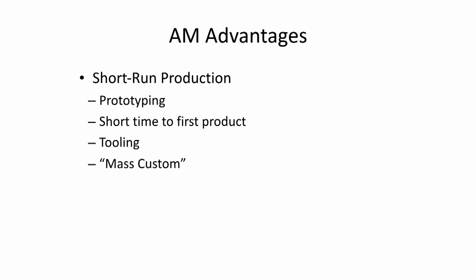Since for additive manufacturing, it's often time that is the limiting factor rather than, say, the number of technicians working on it, the machine may be able to continue on its own, but can only extrude so much material per time. Then having massively parallel systems to produce lots of things at once is usually a bigger advantage than, for example, producing parts in series, whereas an injection molder may make many parts in one mold.